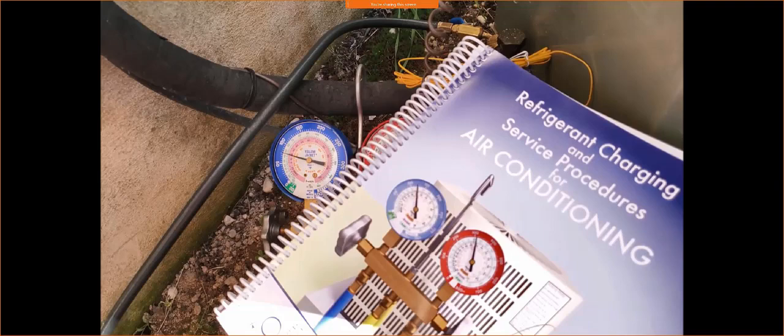And by doing so, now there's not enough air coming back to keep that evaporator nice and warm, all right? Because what we're trying to do is remove heat. Well, now that air was coming in from the basement, all right? That air is already pre-cooled in the basement, and it just kept on working and working and getting colder and colder and colder until it got to the point where it just iced over.